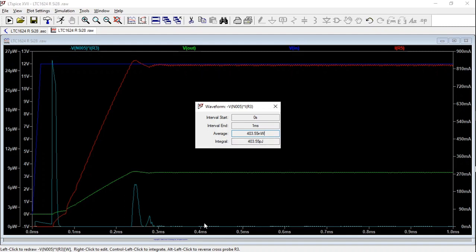And you can see it has briefly two power peaks, after which nothing really happens. It settles down to more or less zero. So it means that a quarter watt resistor is more than adequate.